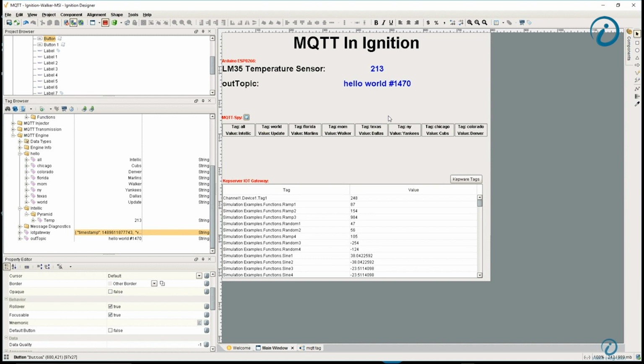And what MQTT will give us the ability to do is essentially create our objects out at the edge on brownfield implementations. But more importantly, with the other Ignition modules, the other MQTT modules here, I could actually read tags from OPC and then use MQTT to turn them into common objects that I can then consume in my SCADA, MES, and OEE implementation.